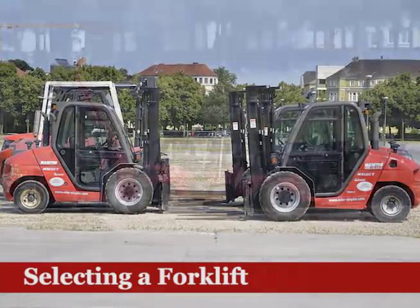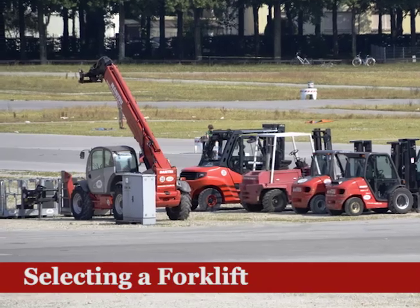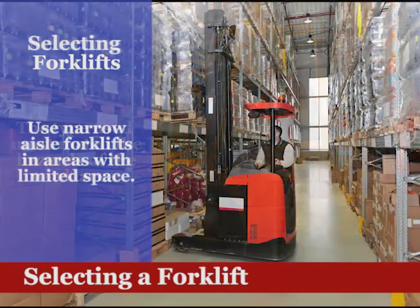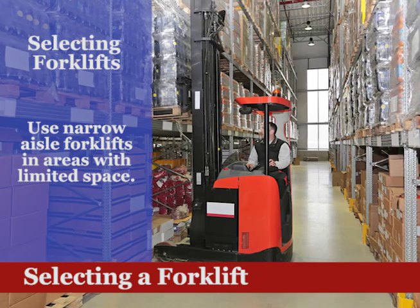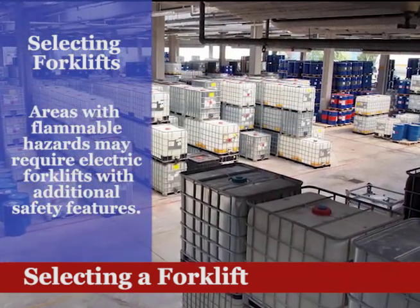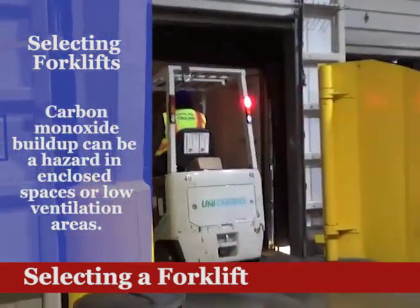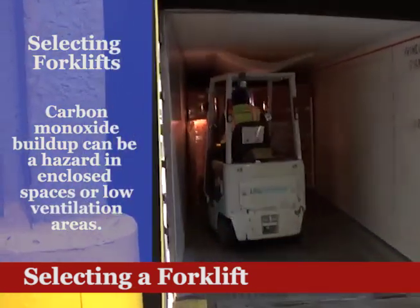As you can see, there are many types of forklifts, each with their own function, power supply, and safety features. It is important to select the right type of forklift for your work environment. Workplaces with narrow aisles and access require a narrow aisle forklift. Areas with flammable gases, or fire hazards, may require an electric forklift, with additional safety features. Closed environments may be susceptible to carbon monoxide buildup, which may require an electric forklift that does not exhaust the harmful gas.